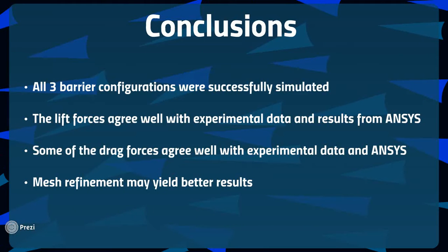So to conclude, 3 different barrier configurations were simulated. The lift forces calculated using OpenFOAM were pretty good, the drag forces not so much. Mesh refinement may yield better OpenFOAM results in the future.